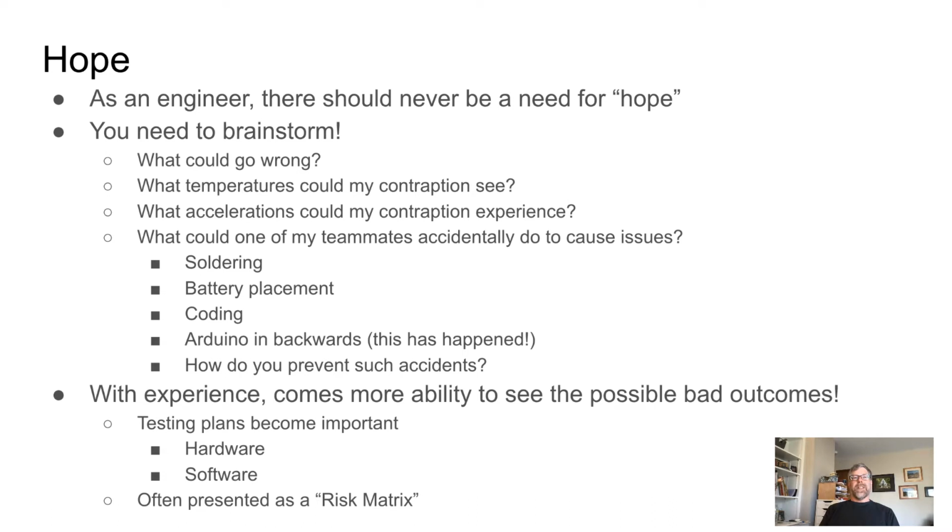And so testing, like what kind of test can you do? Well, you need to think about what type of things could actually go wrong. What type of temperatures could whatever it is that you're testing see? What type of accelerations could my contraption experience? What type of environment might it see? Will it see rain? Will it see salt? Will it see sleet? Will it be just nice and sunny all of the time? Whatever. And then think about, as you're building stuff, what could go wrong.